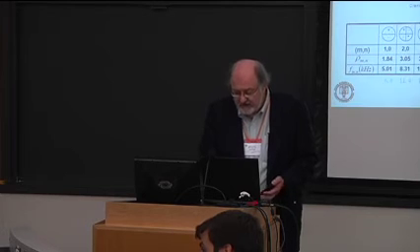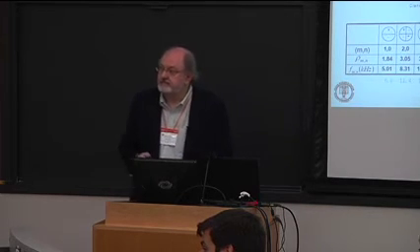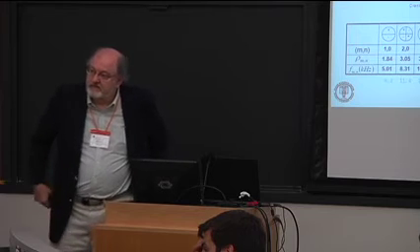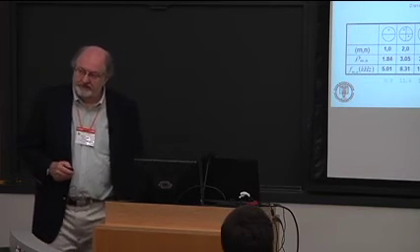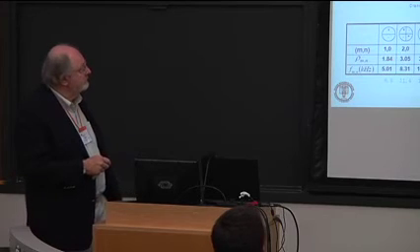Yeah. So you had the picture where you were showing pressure oscillations, and you said that you needed a small enough time step to capture those pressure oscillations. Right. How were you able to differentiate the results you were getting? I guess what I'm trying to say is, is there an effect of your time step on what the solution is? You know, the sensitivity of the solution to time step versus the ability to capture it.